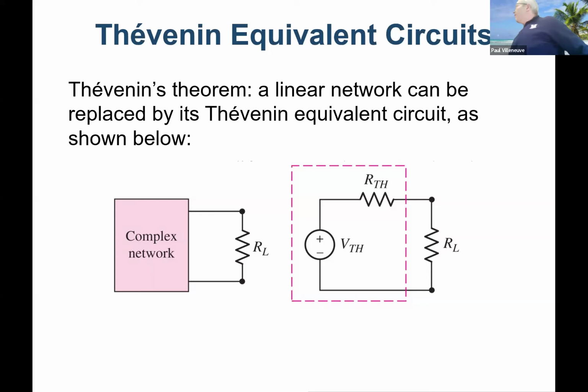So if you look at the Thevenin equivalent, you're replacing a circuit that I don't need to know specific information about. You're replacing this whole network of stuff with one voltage and, this is the other important thing, a series resistor. So that complicated network is accurately represented by two elements. And then I just put a load on it or other additional components to go ahead and do whatever analysis that I have.